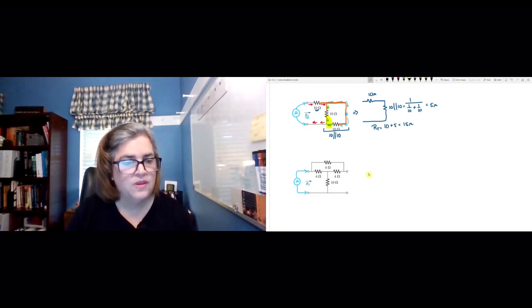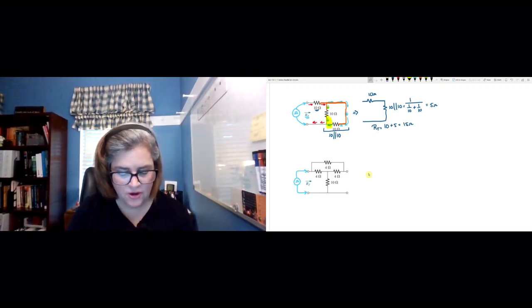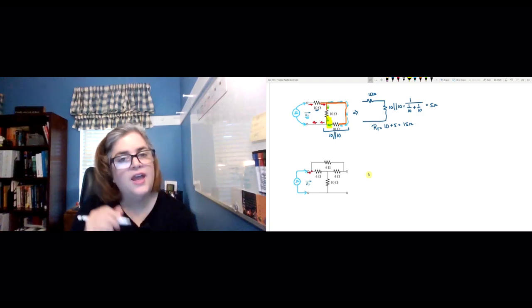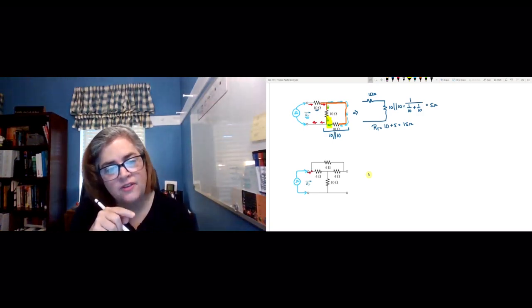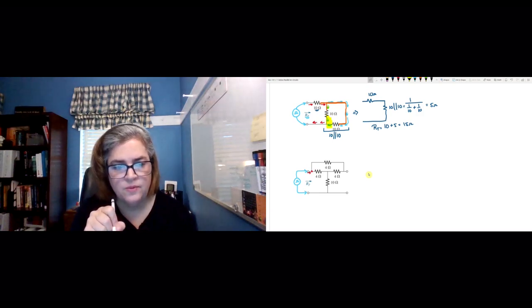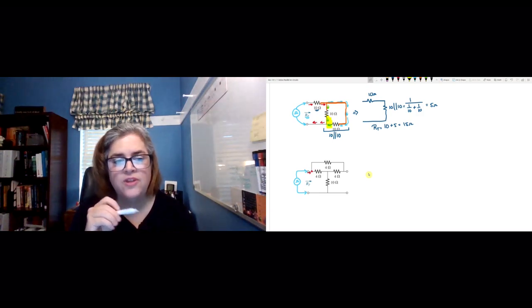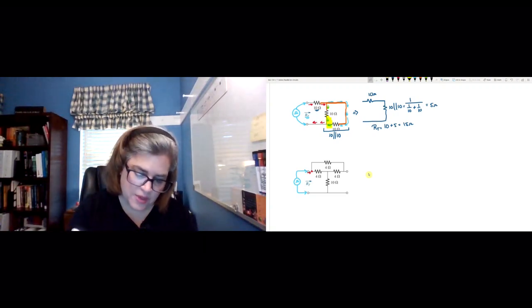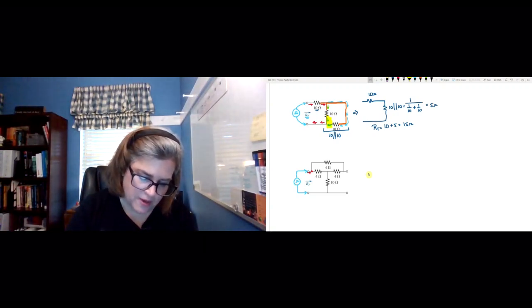Okay, so again, I'm applying my ohm meter here on the left, and then I'm going to trace through the path of current. So when I put a little bit of current here, I notice that there's a little junction here. And the question I want to ask is, will I have any current splitting at that point? Well, it depends on whether that current can get back or not. Okay, so let's just imagine some of the current goes this way. What happens to it at this point?